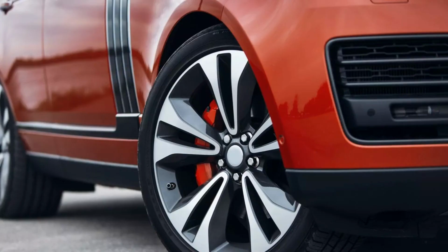All modern vehicles are equipped with vehicle dynamic systems which include, as a minimum, anti-lock brakes, ABS. For the ABS system to work, the vehicle dynamics modules need information on the speed of rotation of each of the four wheels. The ABS system then uses wheel speed information to pulse the brakes during hard braking to prevent wheel lock-up. In fact, when the wheels slide instead of rolling, it becomes impossible to steer the vehicle, which represents